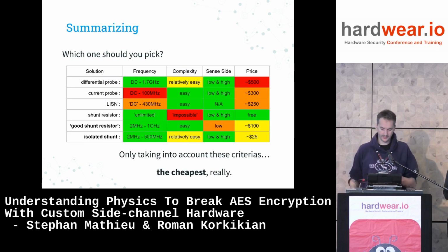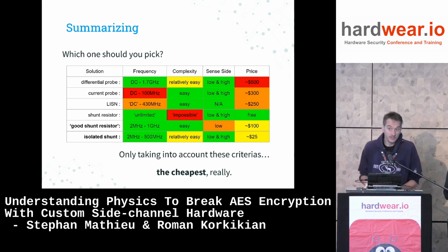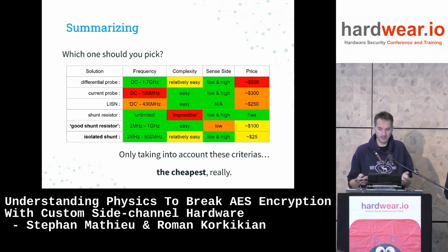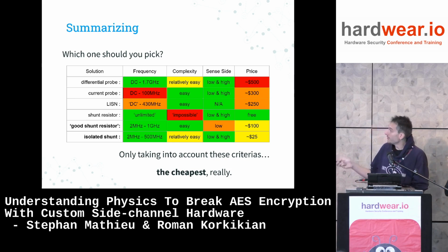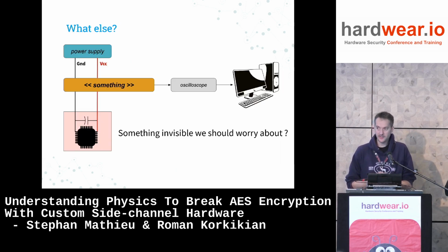So all of these tools presentation, we were talking about bandwidth originally. So if we just take into account the frequency criteria that we're interested in, again, in the case of the ESP32, it was 95 megahertz. Any of them will do. If you just look at the frequency contents, the tools bandwidth, anyone can do 95 megahertz. So if you just took the bandwidth as the selection criteria for all the measurement methods, take any of them, take the cheapest. However, is there something that we should be aware of in measurement method